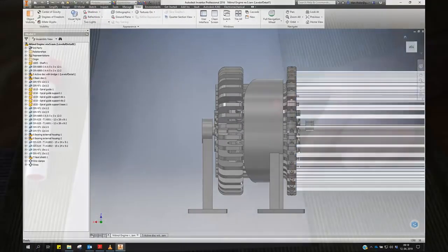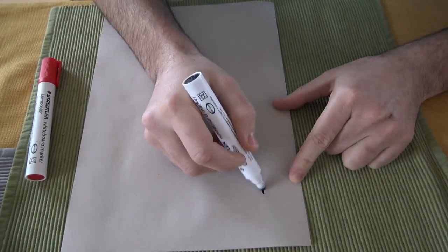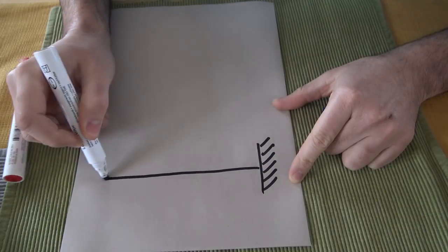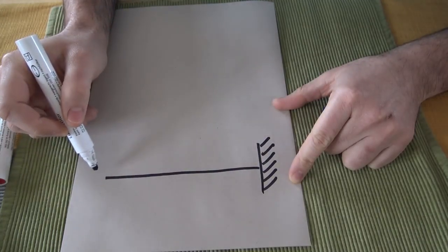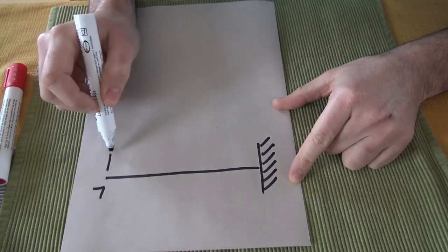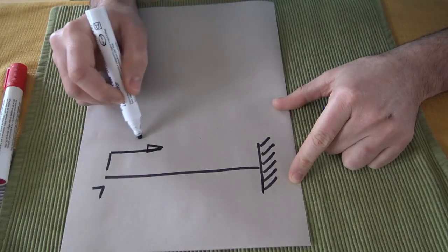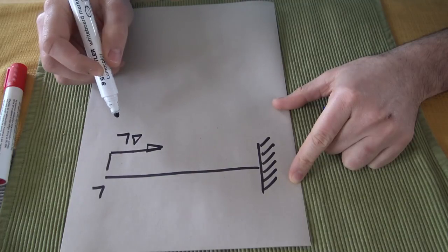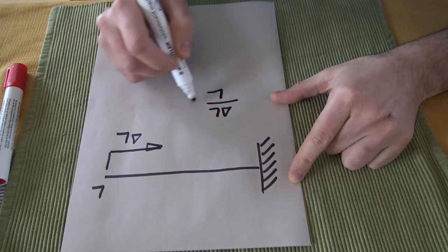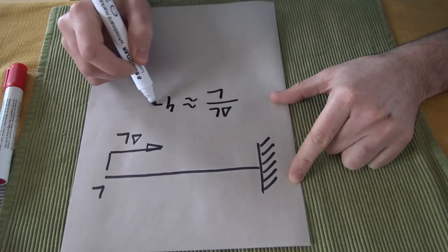Now let's see how the spiral guide redirects the pulling force of the wires dipped in hot water coming from the cold air. First, we need to assume that the wires contract by roughly 4 to 5% of their initial cold length. For example, if a wire is 300 millimeters long, then by dipping in the hot water, it will contract by 12 millimeters. That's the beauty of the memory-shaped wires, especially one in particular that is Nitinol.